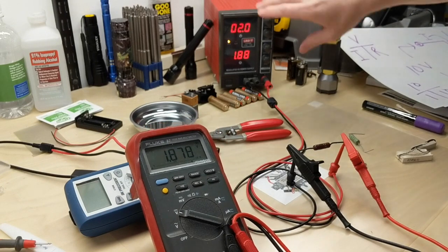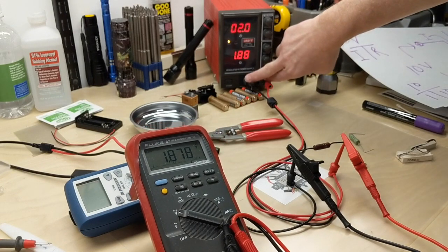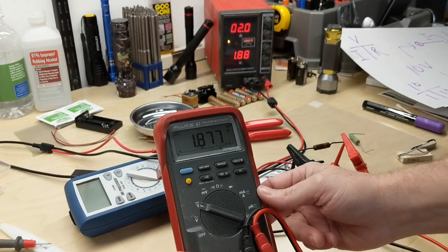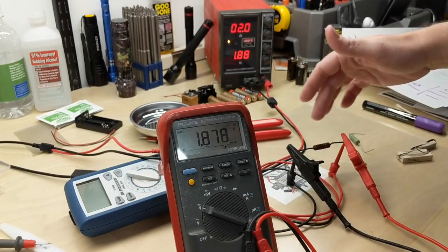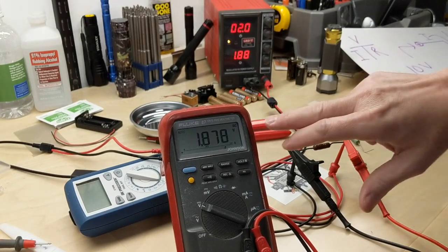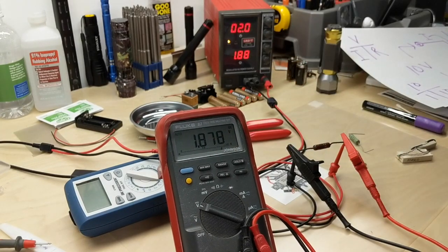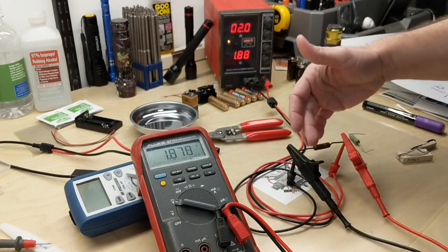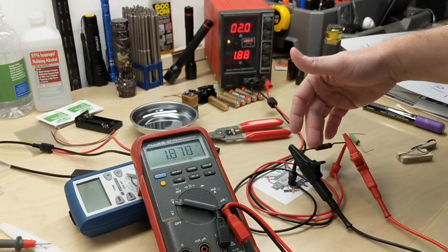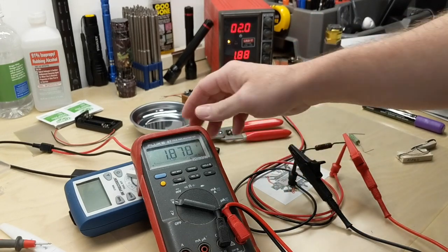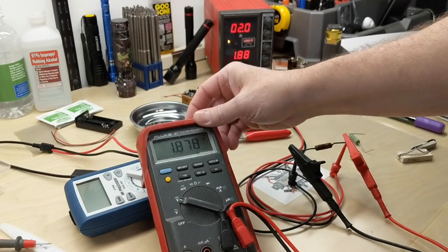Because remember, this 2 volts is from here, so we got some drop here with this load. So measuring the exact same point here, we're showing identical. And this is voltage. So as long as this is a 1 ohm resistor, then the voltage across is going to also show the current.